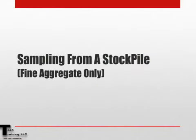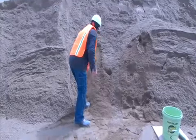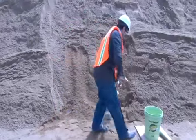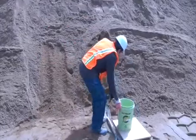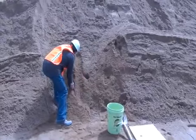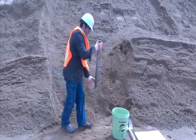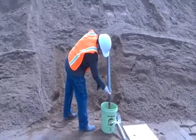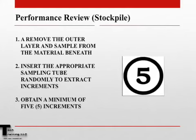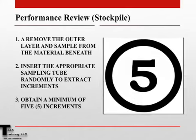Now let's review sampling from a stockpile. This is for fine aggregate only. First, remove the outer layer of the stockpile to expose the material underneath. You can use a shovel or power equipment to achieve this. Insert the appropriate sampling tube. And unlike the other procedures, when sampling from a stockpile, you obtain at least 5 increments.